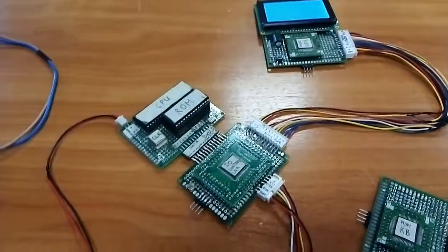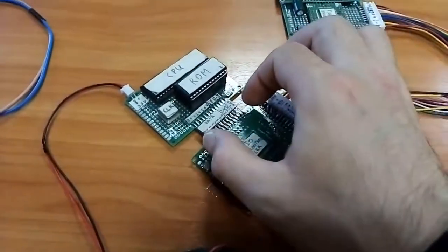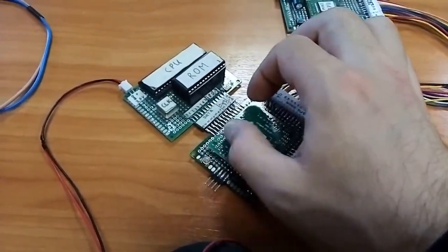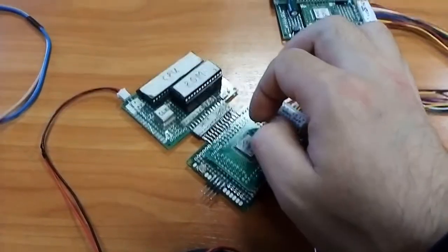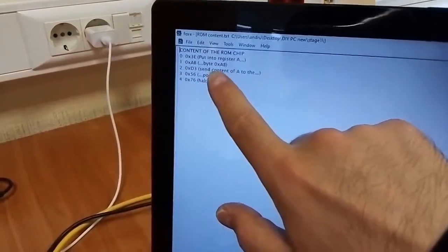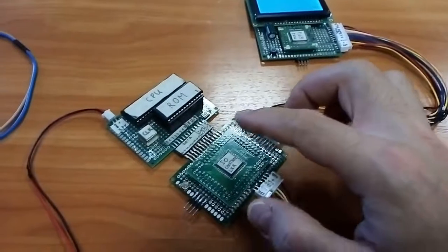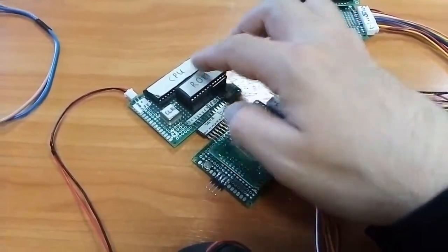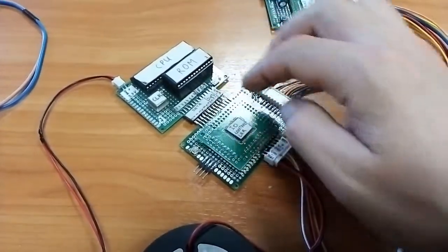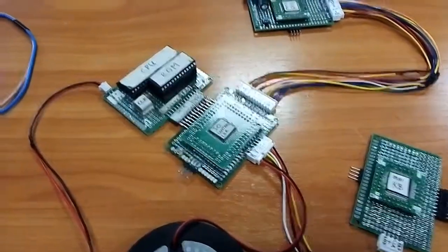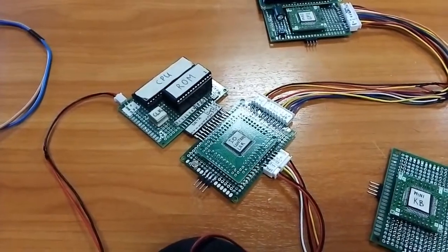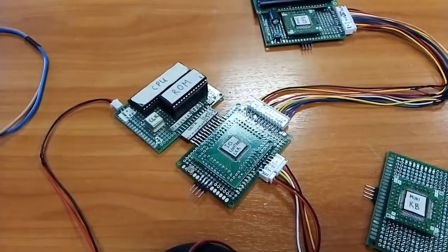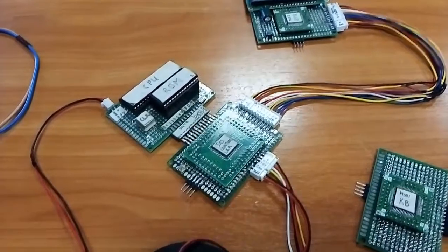In the previous tutorial we connected a flip-flop and light emitting diodes here that showed us this byte AB, as you remember. That showed that the CPU understood the read-only memory program and sent the byte correctly, and that was the indication that the computer works.